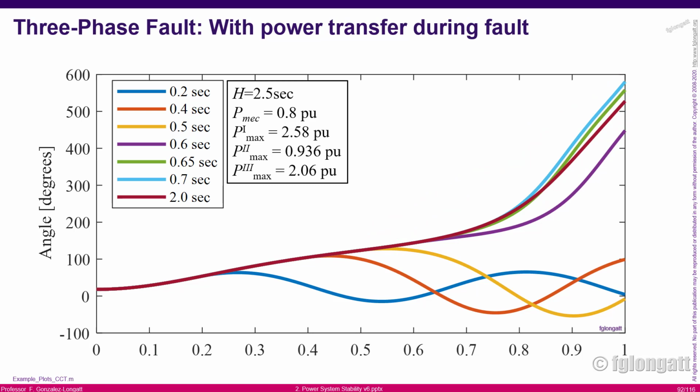What I'm trying to say is it's very important that you understand that when we have a fault, that fault must be cleared, and cleared before the system loses stability. From the power system side, we try to do our best to avoid instability. But from the protection point of view, you must know that number so that you are able to trip your fault without making the system unstable, okay?